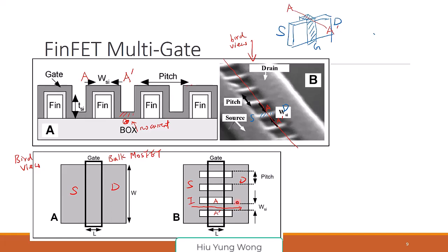So is it not possible to have just one source and drain channel? Oh, I see what you mean. Are you asking why we need to merge the source together for many fins? Yeah, that is just for process issue. One is easier to do. Second is that it provides less resistance, because you can think about it just like the water channel. They come here, then they can just fill everywhere easily and go to the contact. So usually we merge the source together and drain together.